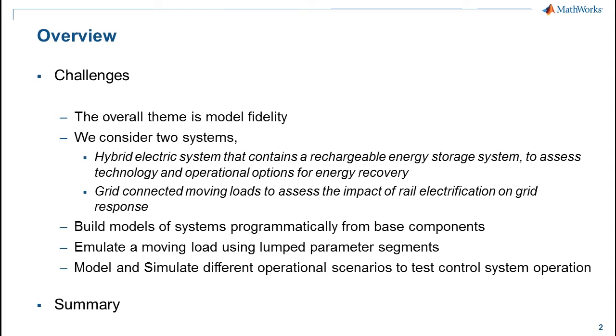When we think about these two examples, both of them can inherently be very complex. For the hybrid electric system, if we are modeling modular multi-level converters, which is what we're going to be looking at here, then we have to think about how we best approach that modeling task. If we're looking at 48-cell, 96-cell architectures or even higher, we need a way that is appropriate for modeling those systems, because we really don't want to put together multi-level converters by hand, especially those systems that have hundreds of individual components.